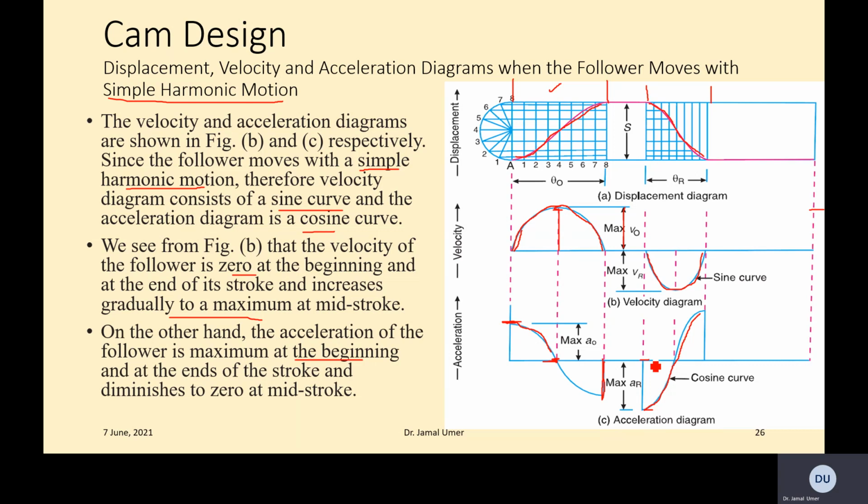We will do a couple of examples, and you will build your understanding from there onward. And one more thing here. Because it's simple harmonic motion, the follower is performing more like a sinusoidal curve, and we are splitting the displacement curve in equal spacing. This depends on the method; when we do some problems, we will see that we are using different methods.